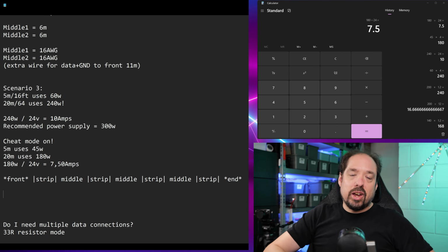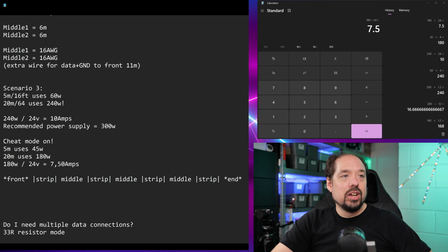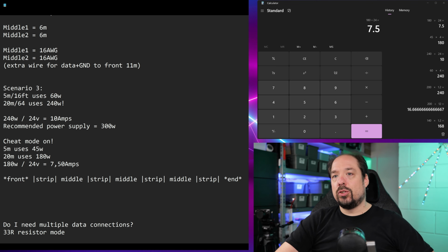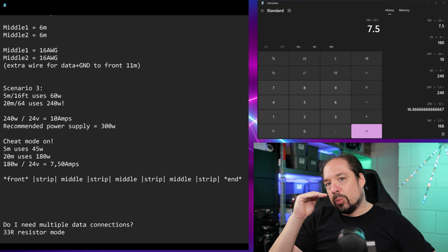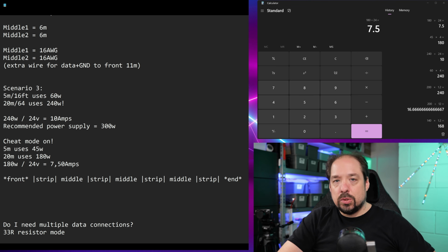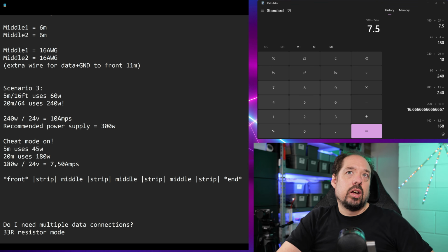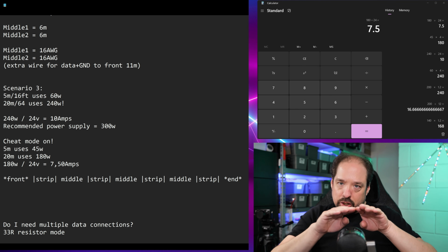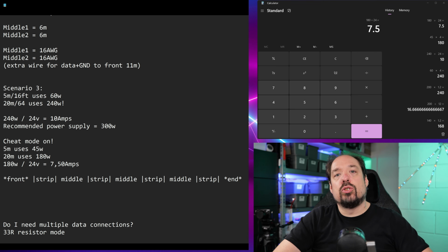But I actually have 4 of these, and I have tested it, and it works fine unless you ask too much of it. As I said, if you want 100% without any voltage drop of dual colors, you will see some dimming in the middle. Unless you limit WLED to 8 amps, but then the whole strip will be slightly limited so that it's still an even distribution of the brightness.